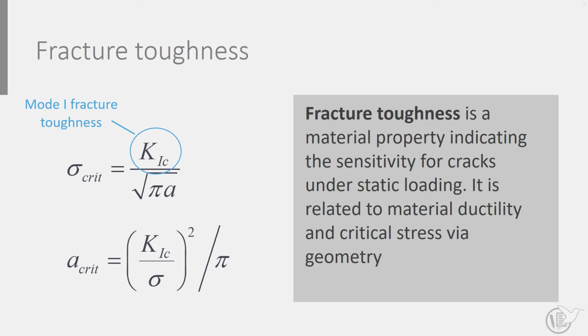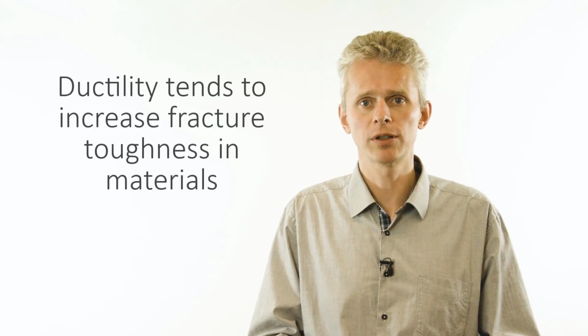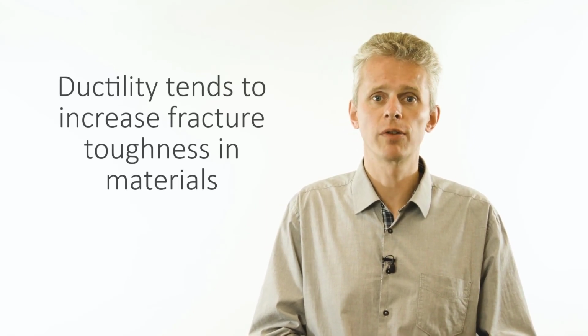or loading. Because the stress intensity factor is an elastic concept, calculation of K is only valid when plasticity is limited to small-scale yielding. In such case, material ductility is observed to influence the value of K1C. The more ductile the material, the more resistant to cracking and failure.